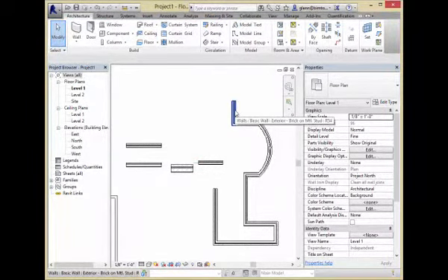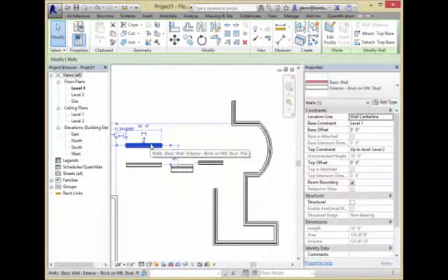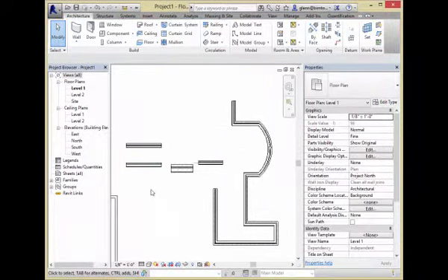Let me show you a shortcut to doing that. Every individual wall you can go through and select. I can click on that wall, I can click on this wall. If you want to grab a second wall, you can control click. That works pretty nicely. If you have something like this, where Revit might be able to infer that it is related, because it's a bunch of connected walls that all have the same type, you can try tabbing, and it'll rotate through different selections. It'll typically select a chain of walls next.